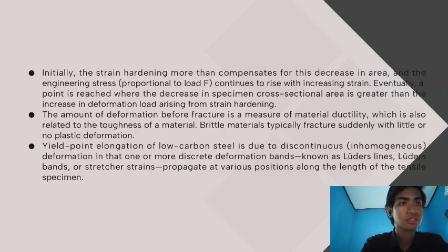But in the latter portion of the test, necking of a tensile specimen occurs, that is, straining begins to concentrate in the region where fracture will eventually occur. This necking can often become so pronounced that the nominal stress will decrease upon additional loading, even though the true stress continues to increase until fracture occurs.